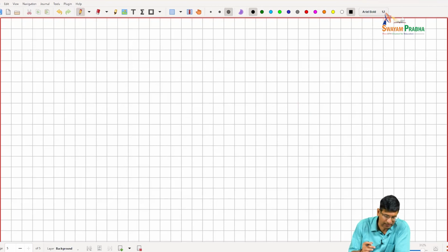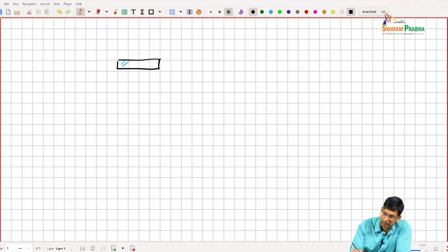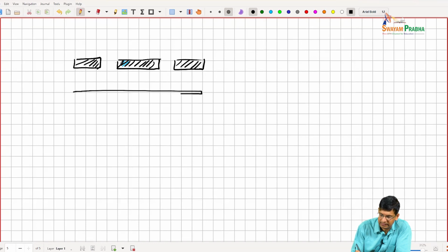So a structure that folks will use is that you effectively have, let's say, a wide signal layer. You have a ground layer, and then in the layer below we place basically strips of metal, right?